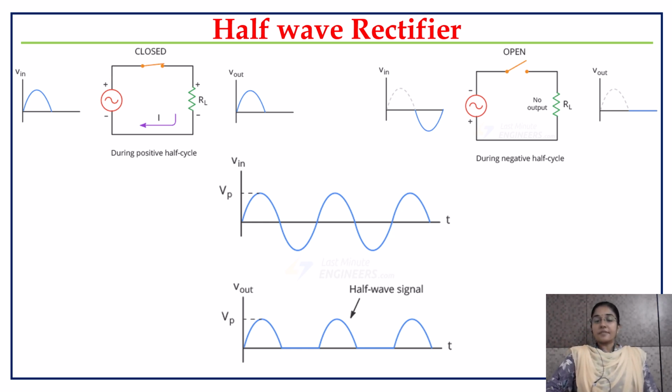So today what have we seen? We have seen what a rectifier is. What is a half wave rectifier? A rectifier is a device which converts my AC to DC by the use of one PN junction diode or more than one PN junction diode. So types of rectifiers are half wave rectifier, full wave rectifier and the bridge rectifier. When it comes to a half wave rectifier, we have a transformer. Along with the transformer, I have one diode and the load resistor.